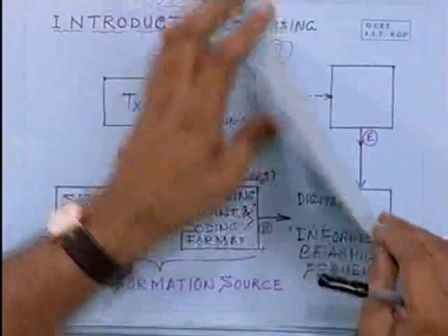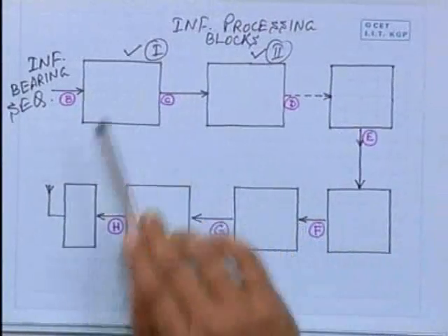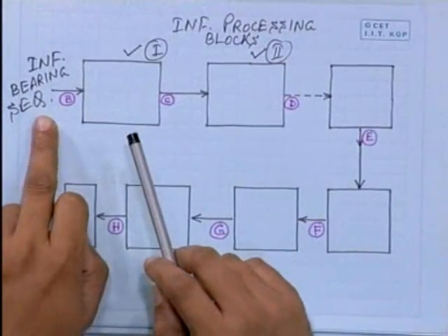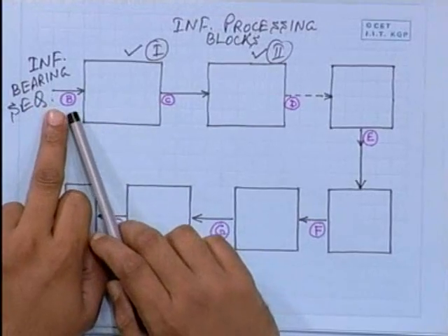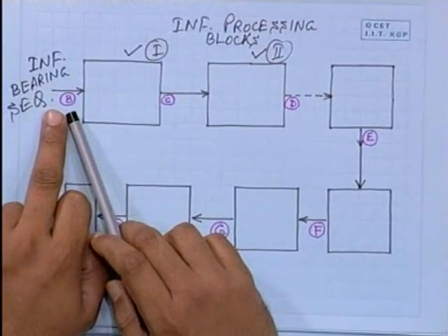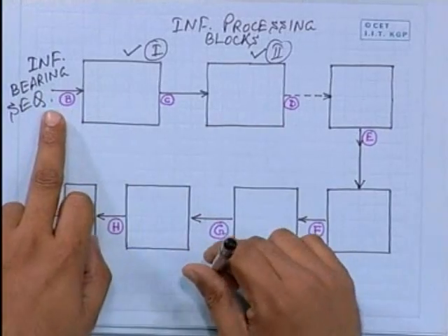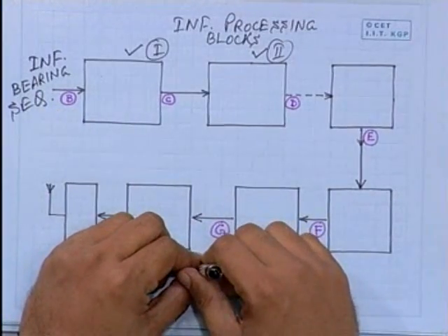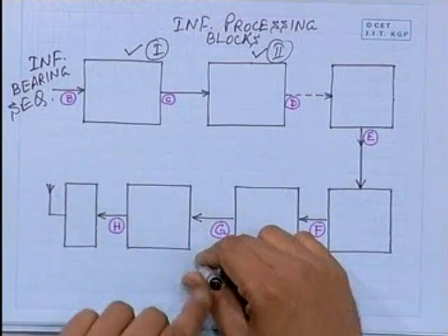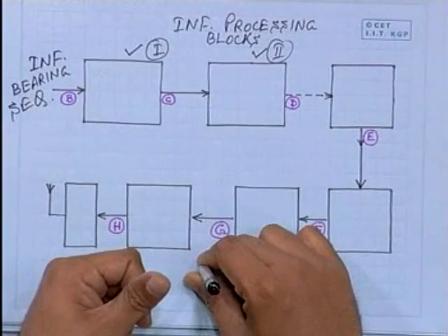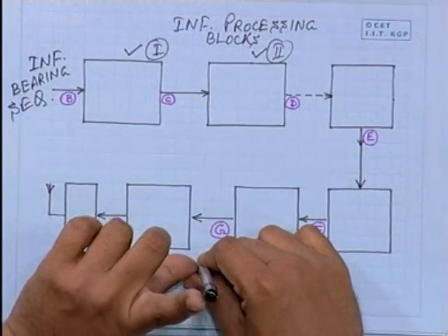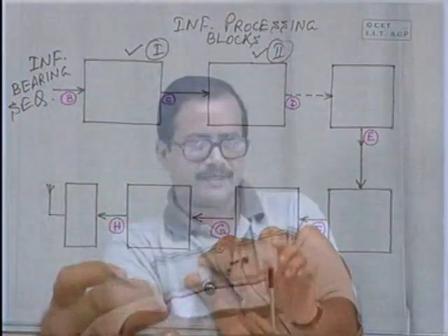I go back to the next diagram. My point is that if I now look at this input sequence of ones and zeros, if I have two very similar samples and I quantize and code one sample by 8 bits, which is a popular standard, we will talk about that, then two subsequent samples from the speech signal are going to be almost of similar height. There will be minor differences.